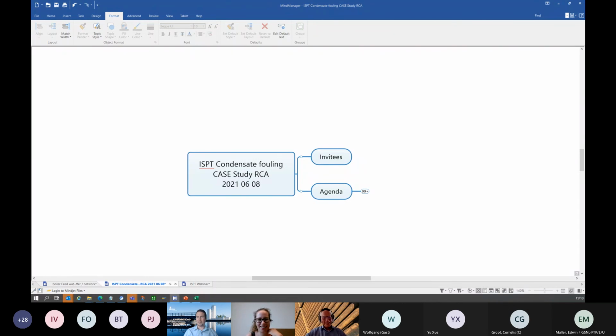Hello, David. Hi, Wilfried. You put it quite well. So yeah, exactly the question as Marjolein posted. It's how much of it would be the relatively clean turbine and reboiler condensate. Well, in this case, we've learned our lesson in the past on using process condensate as input for steam systems. So that's usually not being done. So that was also the new system we were trying to test, or the plant was trying to test, a new process steam conditioning system with the idea to bring it back into the system. But that would then be process steam. And that's a different cycle for us.